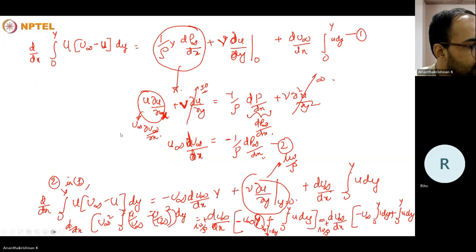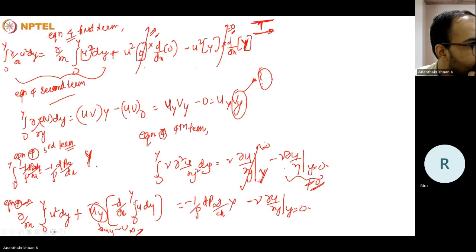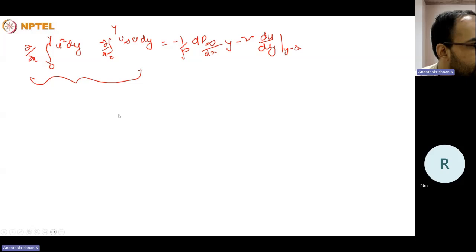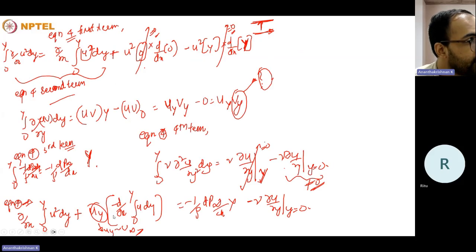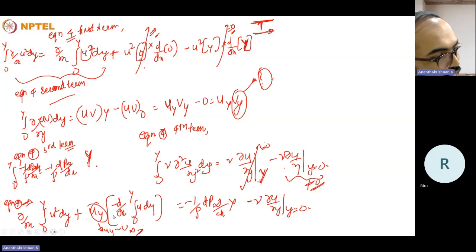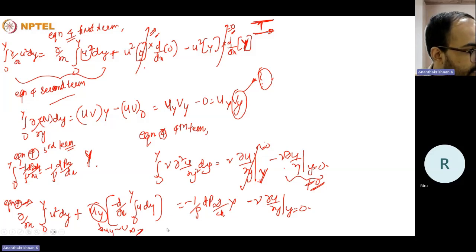So in this step, we have seen uy, we have put this equal to u infinity. But the issue with this kind of analysis is that u infinity, though it doesn't vary with respect to y, can vary with respect to x. If you assume that it's a flat plate, it doesn't vary with respect to the x direction. But if you assume it's a flow through a tube, u infinity will become the core velocity. So that can vary, so you can't directly take it inside this particular derivative d by dx.